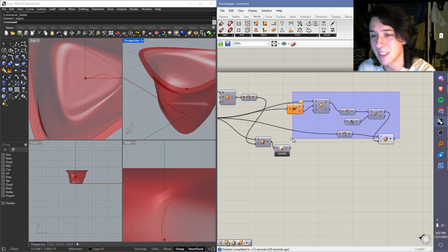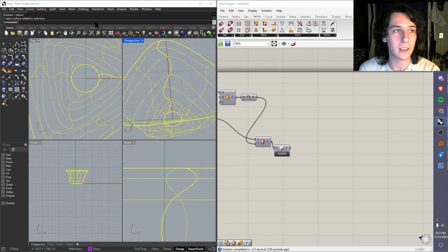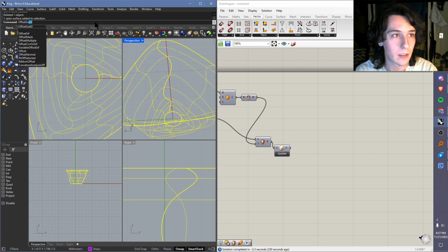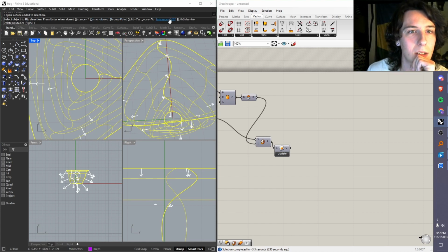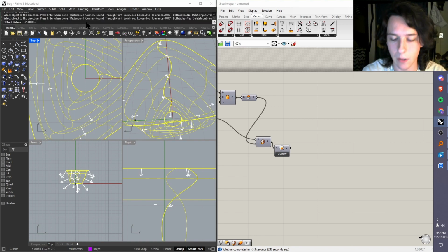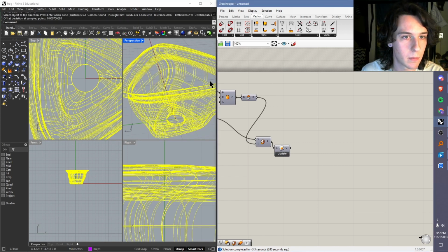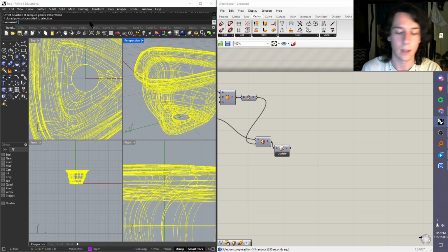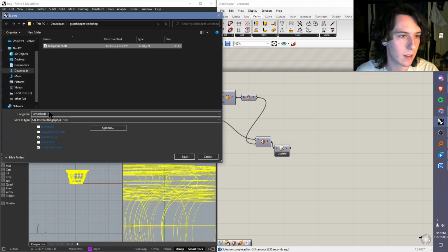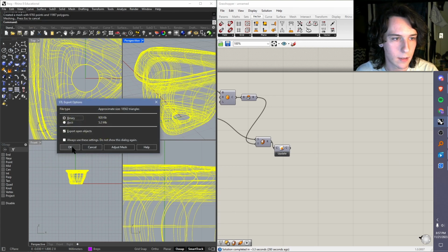Instead of doing all that, we have this shape, right? And we can just select it in Grasshopper and use offset surface. Now, let's do both sides, and let's set the distance to, I don't know, 0.1. And let's just hit enter. Yeah, now you have a closed polysurface, and we can export that as lampshade number 2.stl.